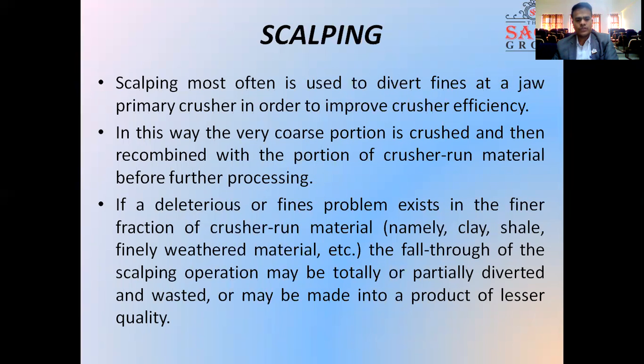If a deleterious or fines problem exists in the finer fraction of the crusher run material, the fall through of the scalping operation may be totally or partially diverted or wasted, or may be made into a product of lesser quality. That means if these waste materials, soil or clay are fed into the crusher, then the product which we get as output has lesser quality.